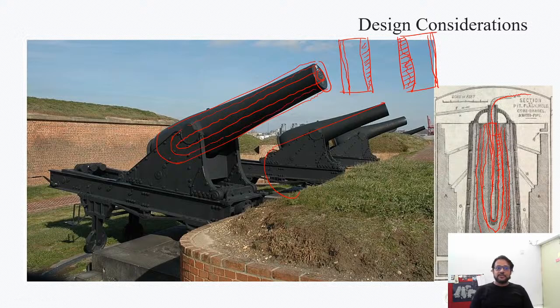So this is an example of a chill which was used to solve a major problem. This simple thing that he did, though I don't think it is simple, it's fairly difficult to execute, was the idea to cool this part at a faster rate than the outer surface. Just that simple idea resulted in a cannon which was so much more reliable. These cannons, I think, are now decommissioned and replaced by more powerful equipment.